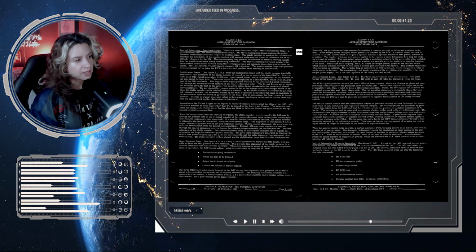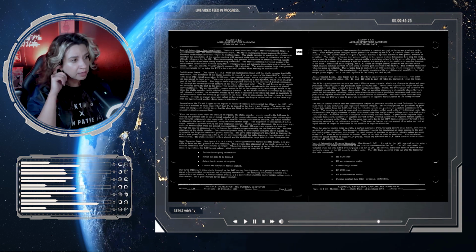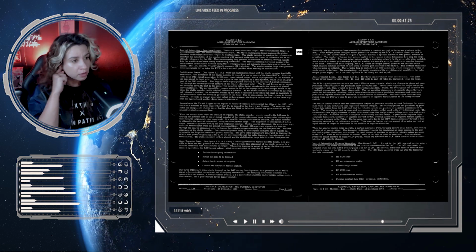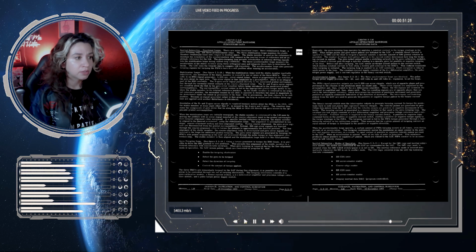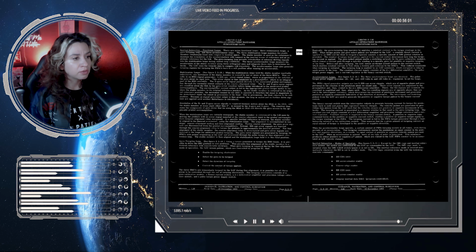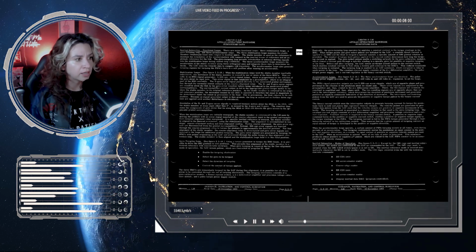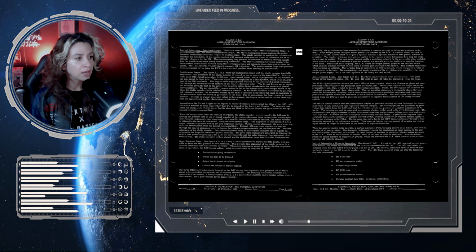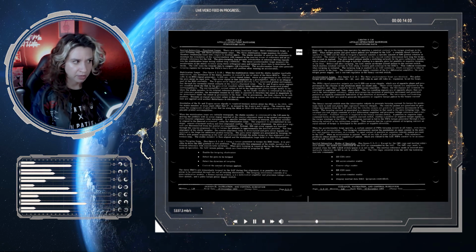Resolution of the X and Z gyro error signals is required because motion about the MGA or the OGA with the stable member at some angle other than 0 degrees is sensed by the X gyro and Z gyro. The resolver then sums the components of gyro error that lie along the MGA or OGA and directs the gyro errors to the applicable gimbal servo amplifiers.